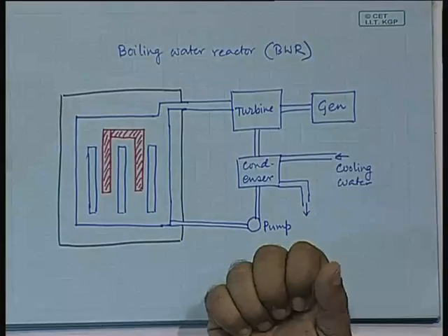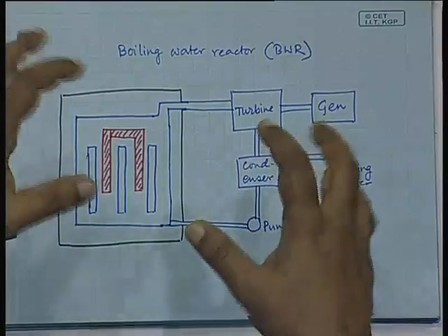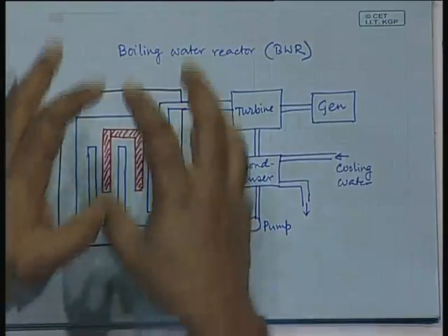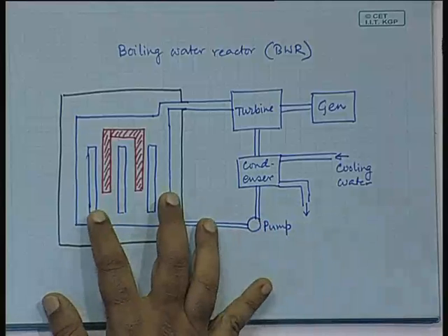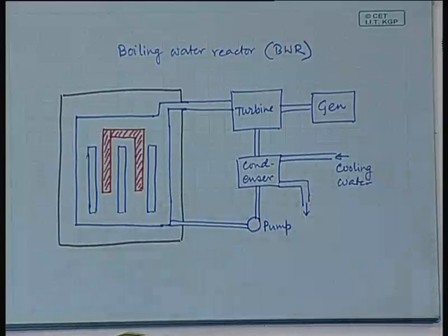Now, here the thing that is coming in contact with the fuel rod is water, and that water at the time is boiling into steam, and therefore a water steam mixture, and steam is not a very good absorber of the heat, right. Water can absorb the heat well, but not steam, and therefore since it is a mixture of water and steam, the overall heat transfer capability, the coolant action is not very strong. Okay. This is another problem of this design of the boiler.